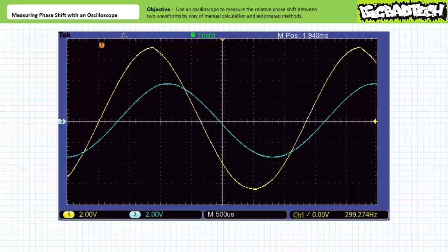One can also make two equally relevant observations about these waveforms in terms of phase shift. Note the blue waveform on channel 2 appears to lag the yellow one on channel 1. Similarly, one can also state that the yellow waveform on channel 1 leads the blue waveform on channel 2. This duality is inherent to the relative nature of two waveforms in that one can only describe a repetitive waveform's position with respect to another. Relativity, as the name implies, relates two quantities with one another, and importantly implies that one of the pair is used as a frame of reference from which the other is measured.